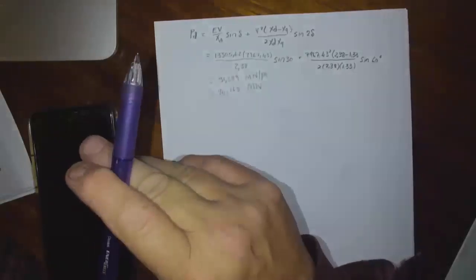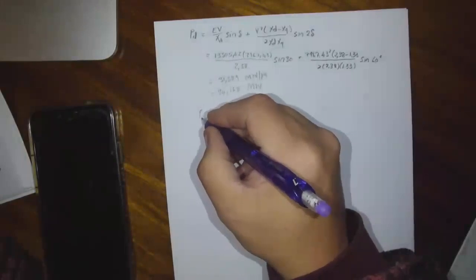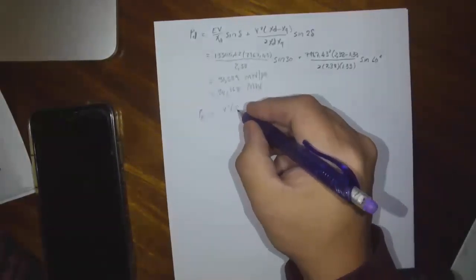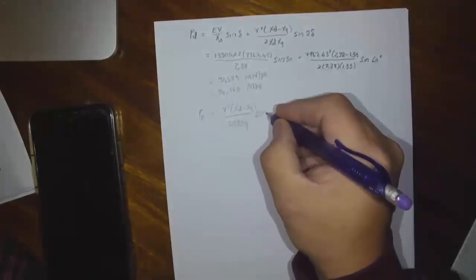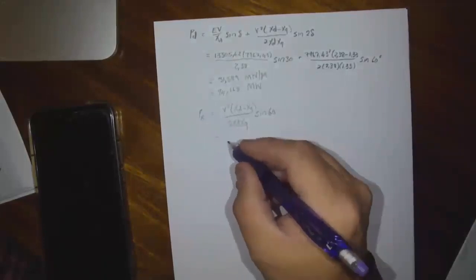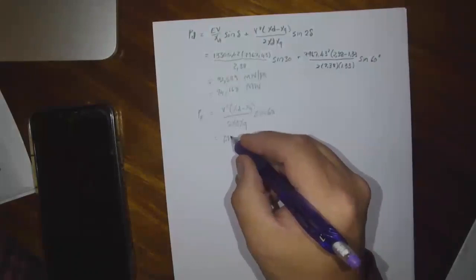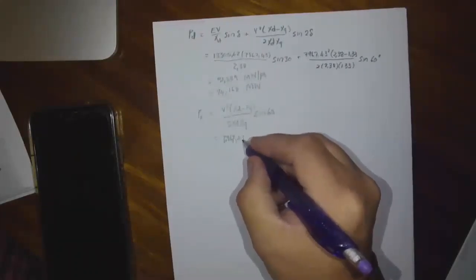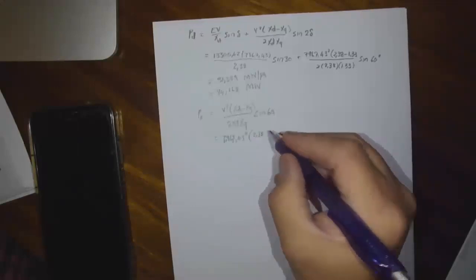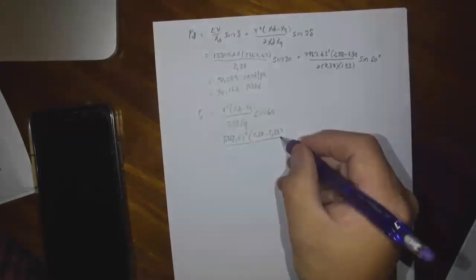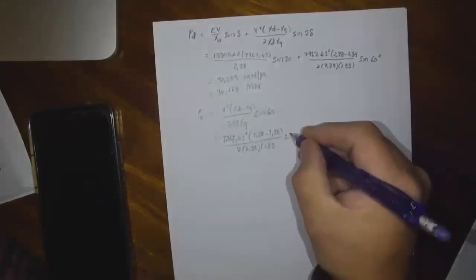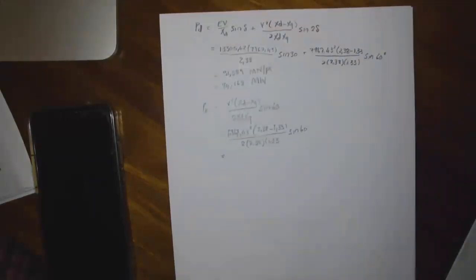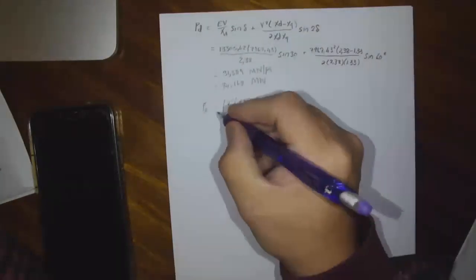All right. Then the reluctance torque. So first of all, we calculate P reluctance, which is V squared (XD minus XQ) over 2 XD XQ, sine 60. That is 796.743 squared, 2.38 minus 1.33, divided by 2 times 2.38 times 1.33, sine 60, and then you get a value there. Now remember, as we are going to use total, it must be times by 3.